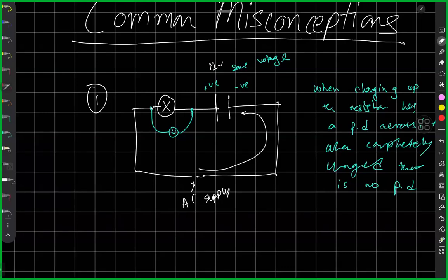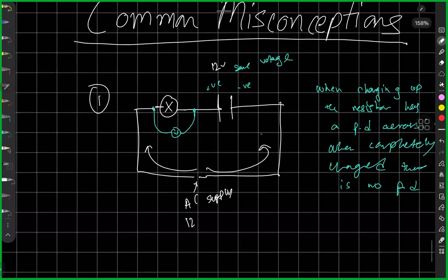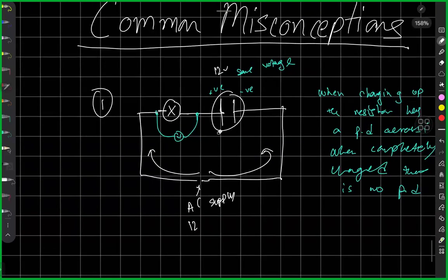Now, what happens if I have AC current? Alternating current. Things are a bit different because it's in the name that it's alternating current. Hence, for half a cycle, I have electrons flowing in this direction. For rest of the half cycle, I have electrons flowing in this direction. Okay. So real current, talking about real current, electrons can flow in this direction or in this direction, both. Half cycle, half cycle, half cycle, half cycle, it keeps alternating. And what happens in that case is the capacitor goes through a process of charge and discharge constantly.